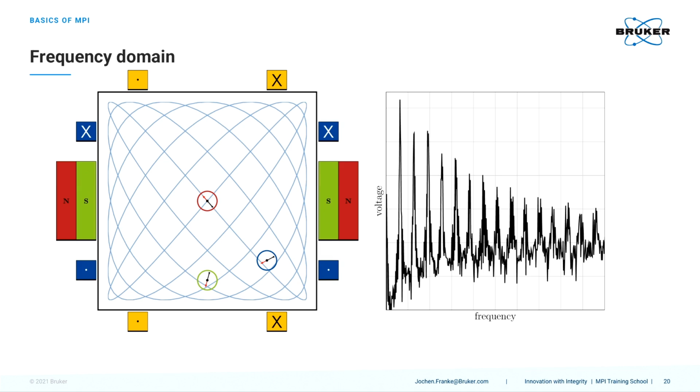So what we are using is to transfer the time signal into frequency space, to have the spectra, the voltage over frequency, and now we can appreciate the two different frequencies injected for X and Y, and the harmonics originating from these ones.